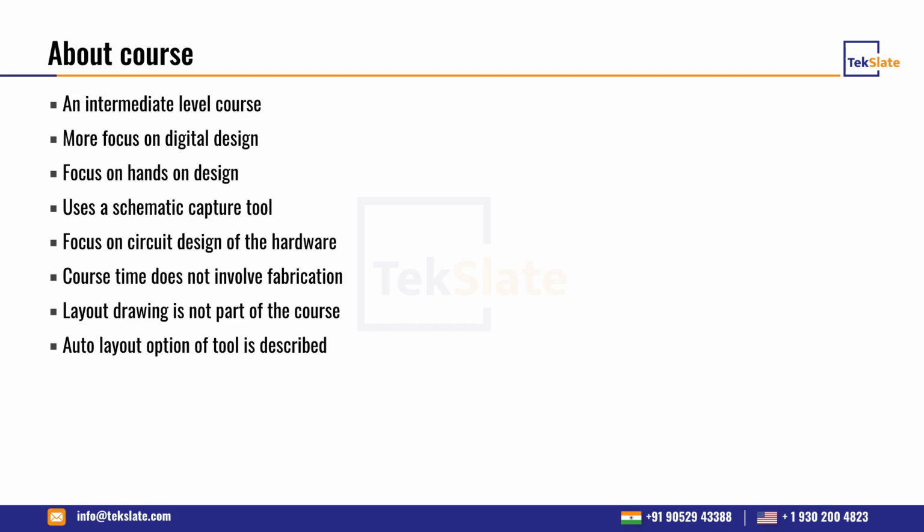A schematic capture tool is recommended and is used in the training. Schematic capture is where we start. The focus is on the circuit design of the hardware, definitely. How the components are selected, how they are connected, what the interfaces are, the signaling, the purpose of each of the signals, and the timings of the signals. Those are covered in the circuit design.